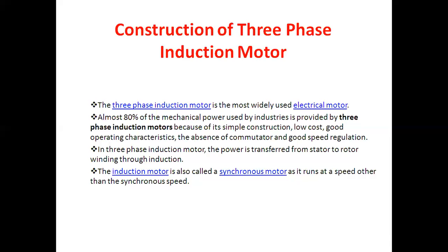In a three-phase induction motor, the power is transferred from stator to rotor winding through induction. The induction motor is also called an asynchronous motor as it runs at a speed other than the synchronous speed. So this is the basic idea of a three-phase induction motor.